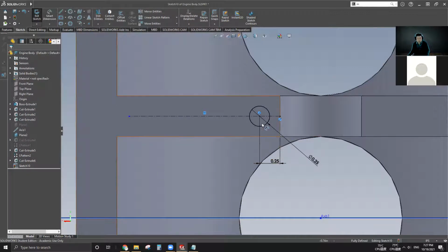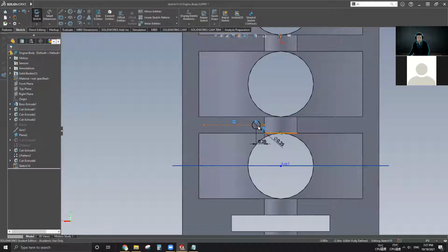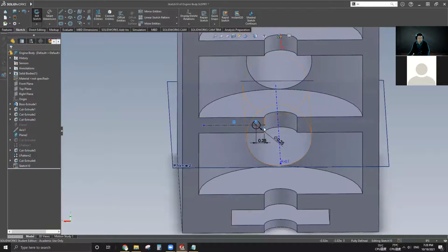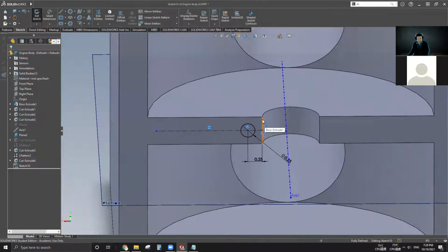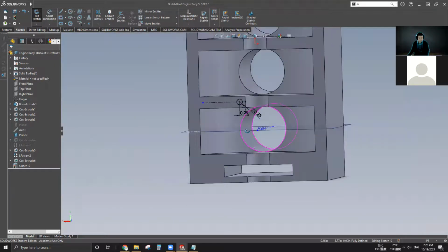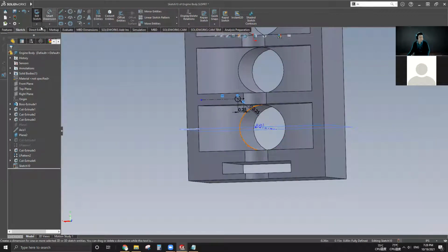However, in reality, for hole position, you need to remember, we just talked about true position last week, right? For hole position, you cannot reference some edge that's not a straight edge. This is part of a circle. So the machinist who is trying to locate this hole will have a very hard time defining the 0.25 from this edge. So just keep in mind, in the real world, you need to have the dimension labeled from this edge or that edge. I'm just saying, but in this case, we just do it like this.